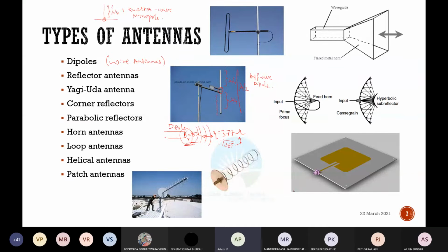So it's an imaginary thing, but that effect is available. Had there been a resistance of this much, 75 ohms, how would the signal propagation take place? That is the effect which this phenomenon brings in. So therefore we consider the radiation resistance. So this side it is 75, that side it is 377. So not matching. So dipole has very less efficiency.